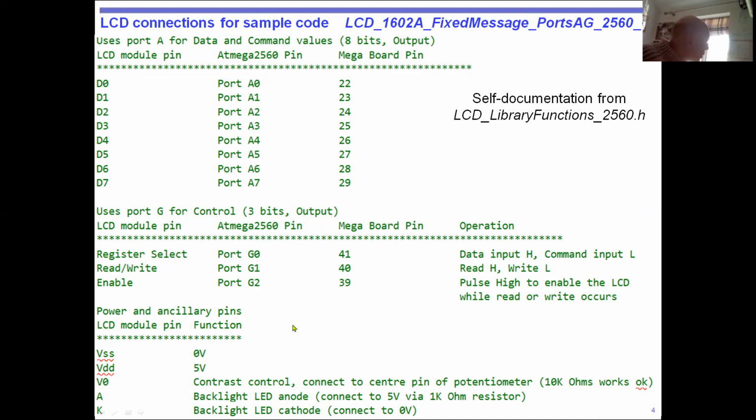And then we also have some extra wiring for the power supply and a variable resistor, which is also in your kit, or it used to always be, with 10 kilo ohms, or, well, that works okay. A higher value will also work fine. And you will basically connect your LCD, your variable resistor will have one wire connected to that, the other to that, and the mid wire going to V0. And this is just basically a contrast control.